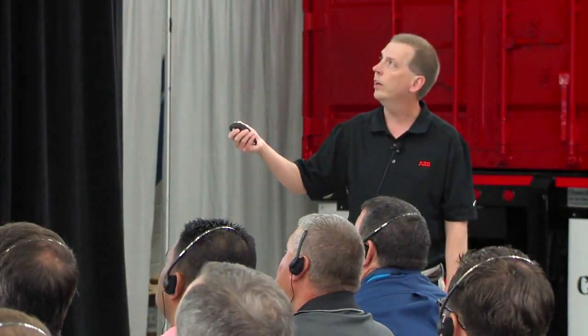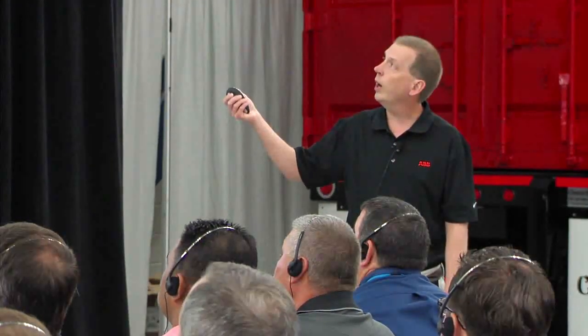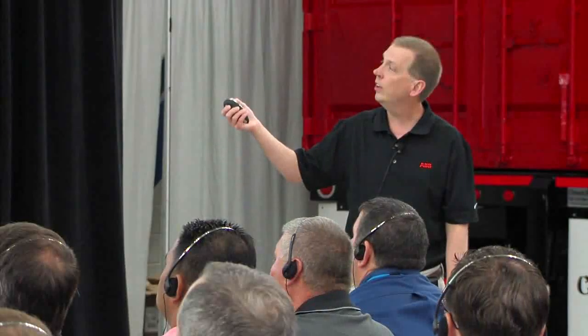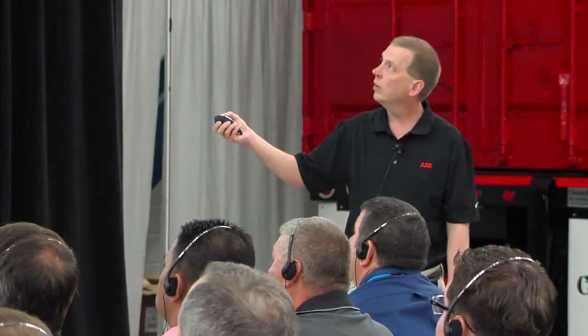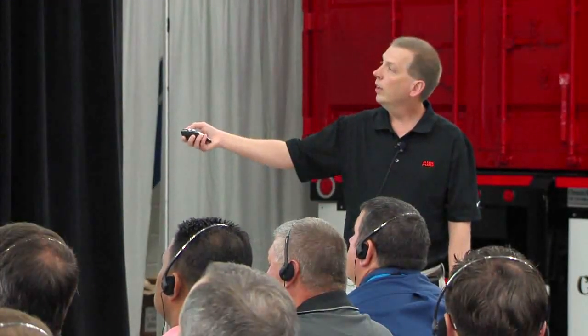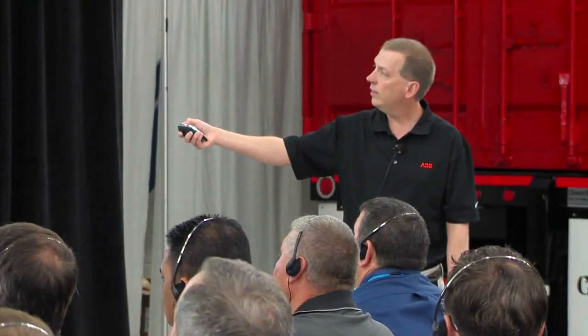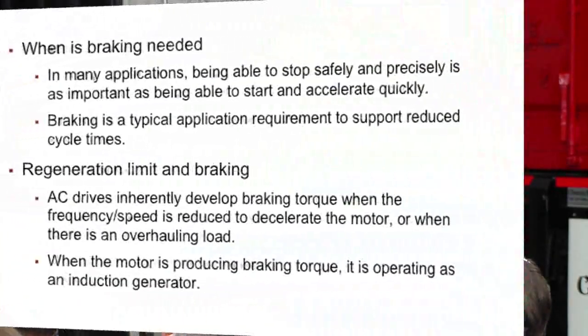And then this is the DC brake time. This has to do with the DC injection here in the slide before. Back here. Here, when we start injecting DC, how long do we want it to inject DC for? That's a parameter we can set.